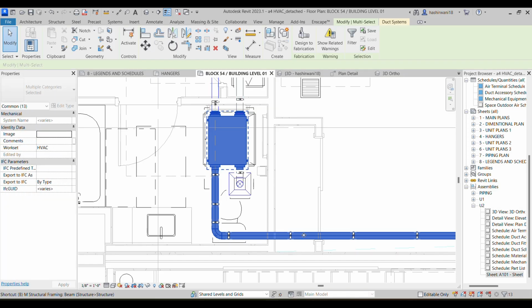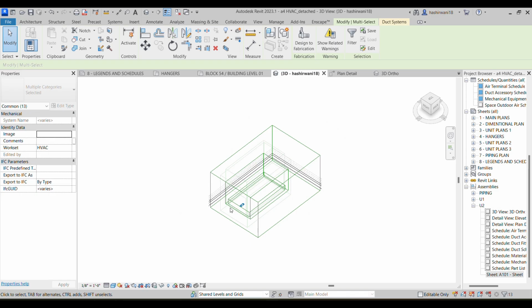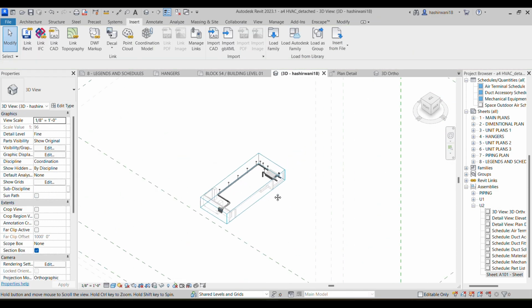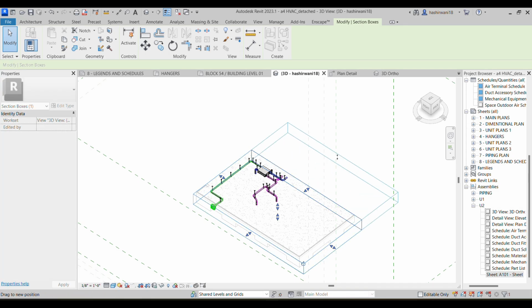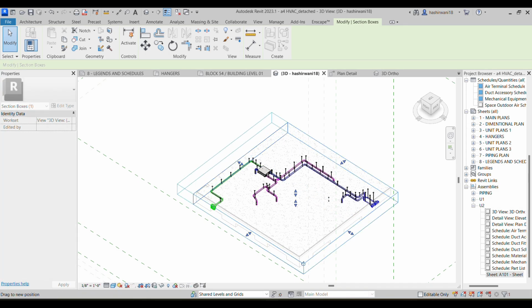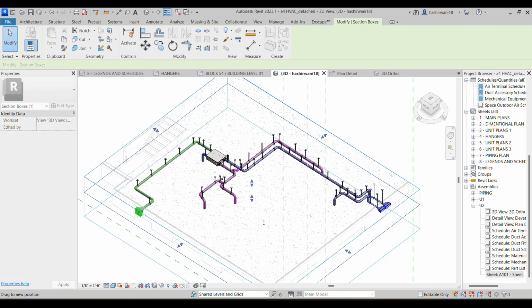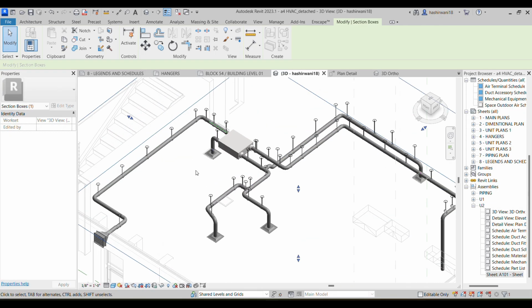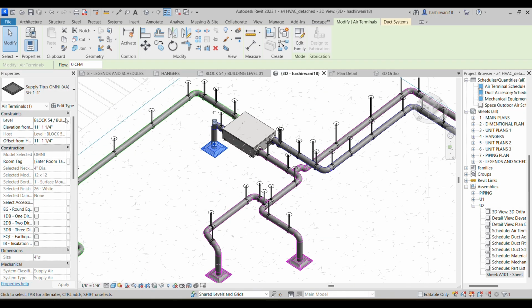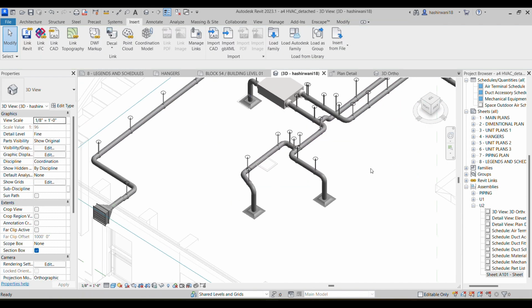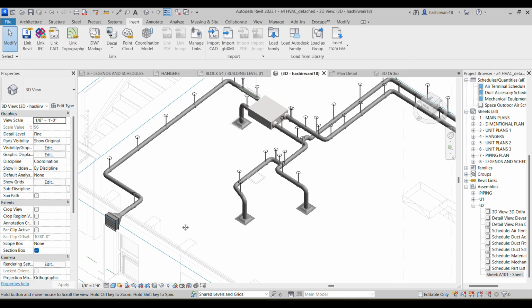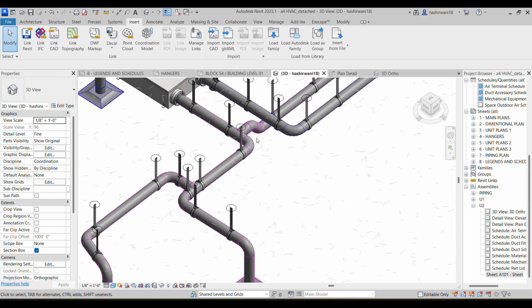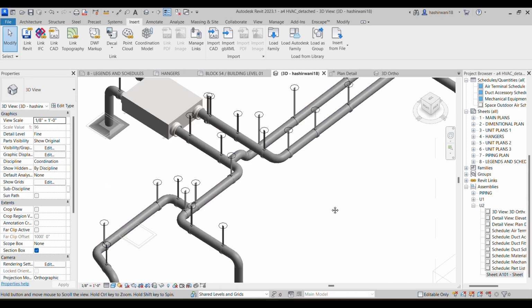Okay, BX now, select BX now, maybe, yeah. Can you see I've placed an ERV unit here. I've made some exhaust grills here, stub downs here, and then placed some air terminals SG1 to 4, etc. I think you guys can do this, it's very easy. We have placed some louvers here as well, and made sure that these don't clash with each other.